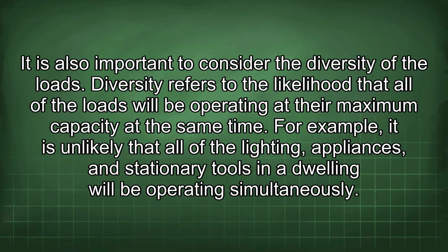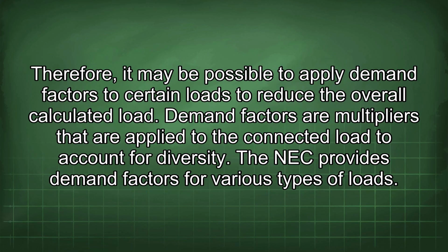It is also important to consider the diversity of the loads. Diversity refers to the likelihood that all of the loads will be operating at their maximum capacity at the same time. For example, it is unlikely that all of the lighting, appliances, and stationary tools in a dwelling will be operating simultaneously. Therefore, it may be possible to apply demand factors to certain loads to reduce the overall calculated load. Demand factors are multipliers that are applied to the connected load to account for diversity. The NEC provides demand factors for various types of loads.